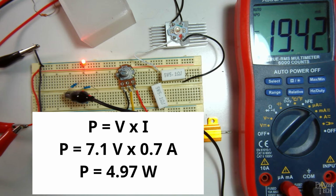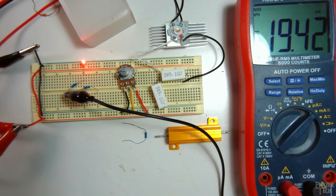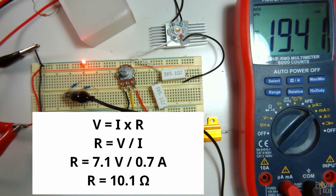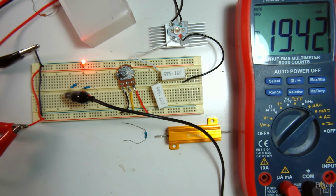So let's say we wanted to get close to its maximum brightness. This is an example where you'd need to use a resistor with a higher power rating, such as these 5 watt cement resistors. But if we wanted to provide 700 milliamps to the LED, we would also need to change the resistance value as well. 7.1 volts divided by 700 milliamps equals roughly 10.1 ohms. Now these particular cement resistors I have are only 5.1 ohms, but if I place 2 of them in series like I did here, that would give 10.2 ohms. So that should work out just fine.